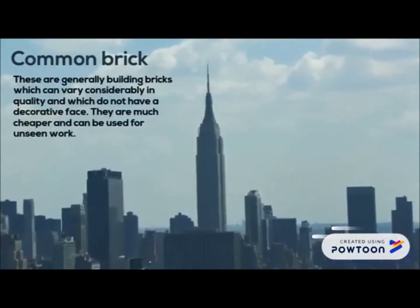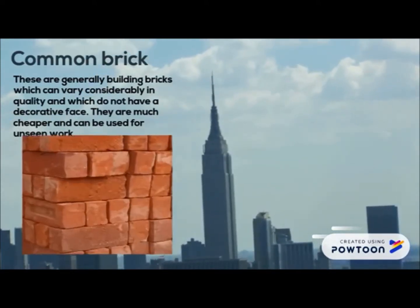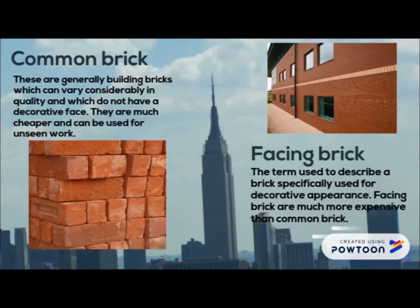Common bricks. These are generally building bricks which can vary considerably in quality and which do not have a decorative face. They are much cheaper and can be used for unseen work. Facing bricks. The term used to describe bricks specifically used for decorative appearance. Facing bricks are much more expensive than common bricks.